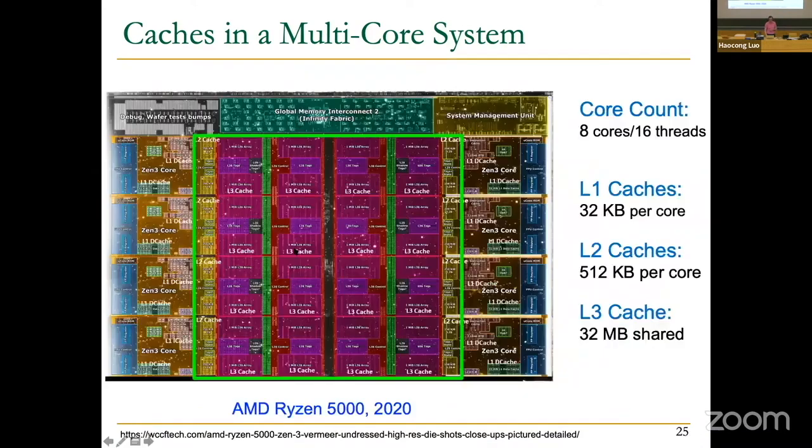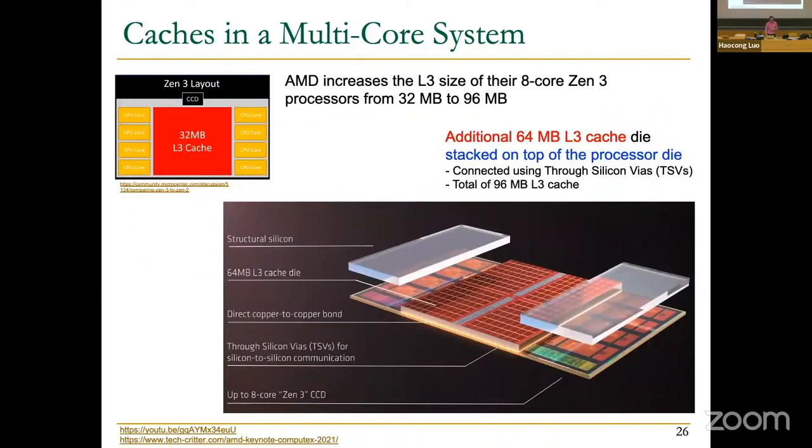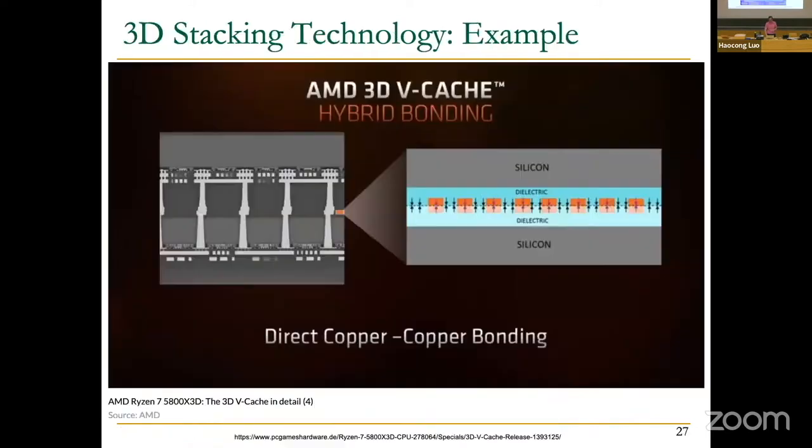So you're used to these pictures right now. I will mention this cache over here because it's very interesting. This is a shared cache that's on a different chip. So basically, they've decided to add these other chips that are bonded on top of a processor chip. And the whole purpose of the other chip is to cache. And there are a lot of actually really interesting technology issues, like how do you align the interconnects in this chip with this chip over here so that they can actually communicate with each other nicely. So there are a lot of fabrication and reliability issues over here that we take for granted right now.